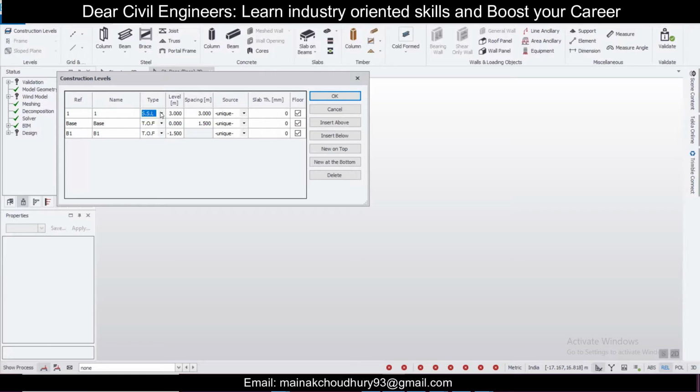Others can be TOF and SSL. TOS, or top of steel, can be used when you are designing steel structures. Okay, give this a slab thickness of, let's say, 100 mm, or you can give 125 mm here to start with, and after that just insert another floor above. So it is basically now G plus 1, ground floor plus 1 floor, a two-story building with 2 bedrooms.